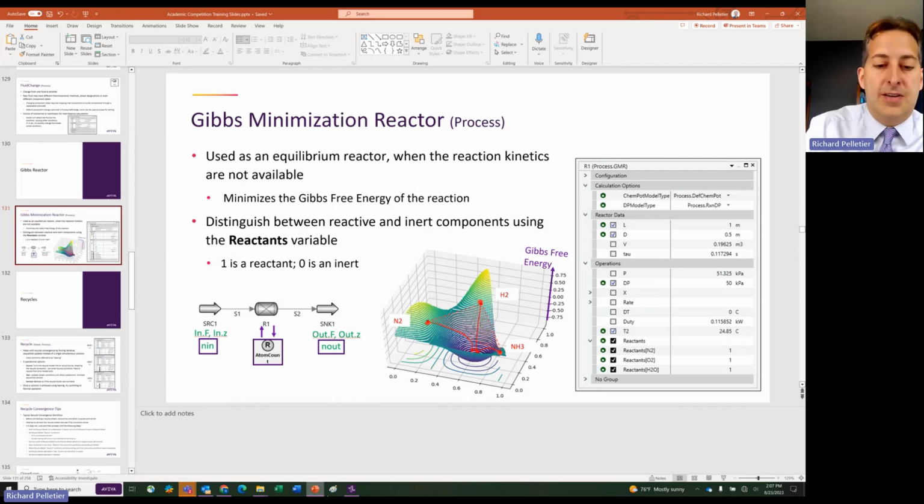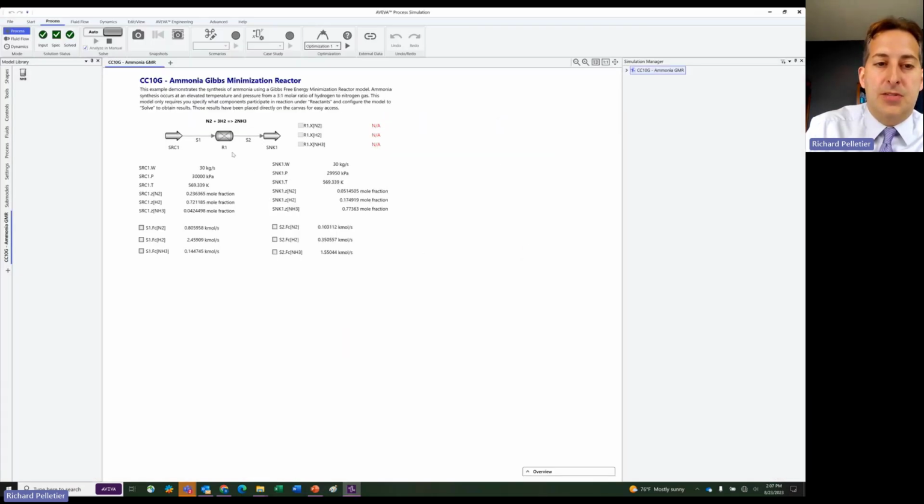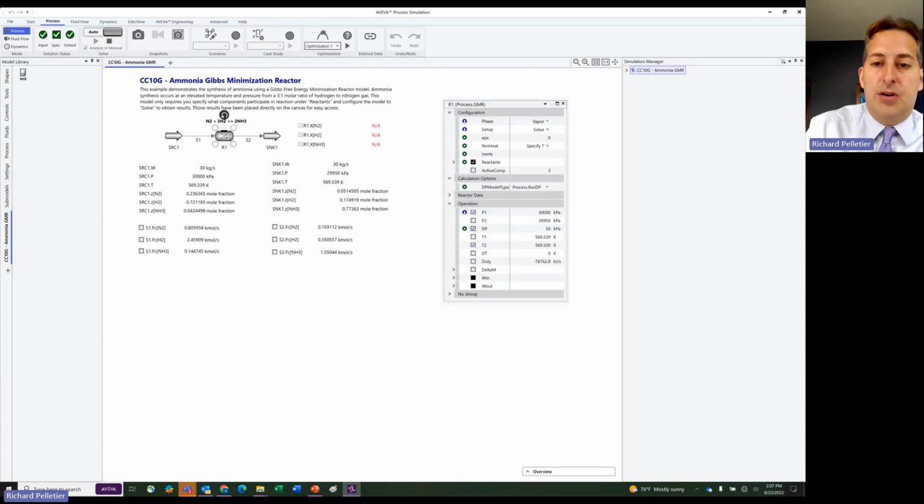It really is as simple as that when it comes to the Gibbs reactor. If there are no values for these components, or the values aren't lined up properly, you might not see the reaction occur the way you expect because the property information might not be adequate. It's all based off of that one property in the component property information.